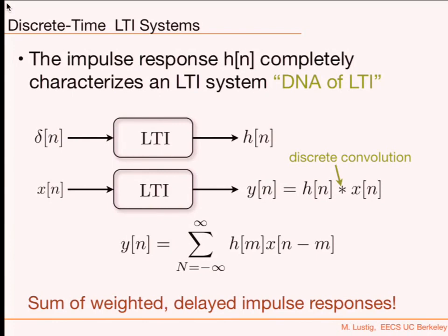So nonlinear operation, so powerful. Look, just a simple operation, just a median filter. Not sophisticated, trying to figure out a spectrum, blah, blah, blah. No, just a median filter, done. Removed everything, almost perfect reconstruction. That's incredible, right? What is the statistics of the noise after that? Kind of hard to then estimate, right? So there are advantages and also disadvantages.